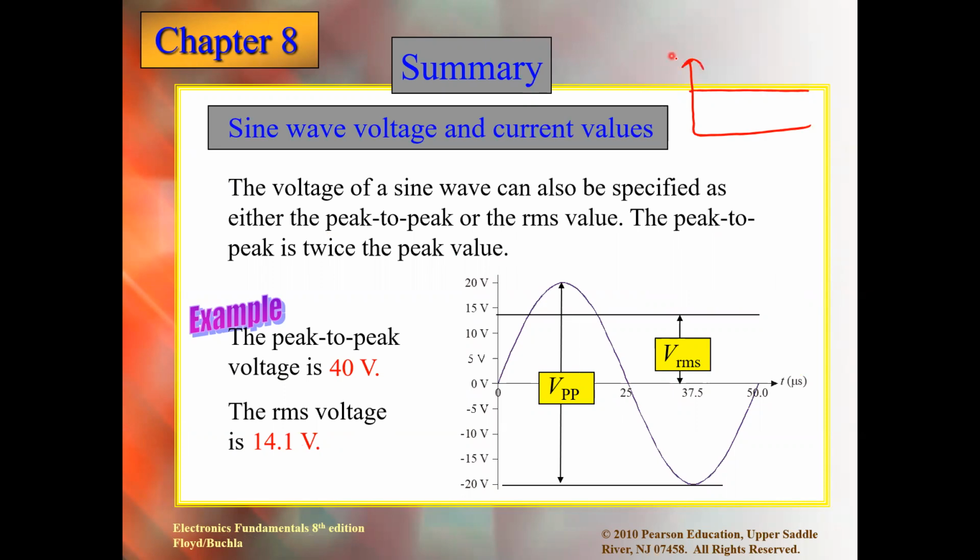For example, if we have voltage here and time here, we say 5 volts, that is, its value is constant, always 5 volts. But in AC, it keeps on changing. You can look here, right? So after getting RMS, as I told you, the RMS value gives you the DC equivalent of the given AC. So this is a constant value. It is 14.1, that is, the DC equivalent of this given AC voltage.